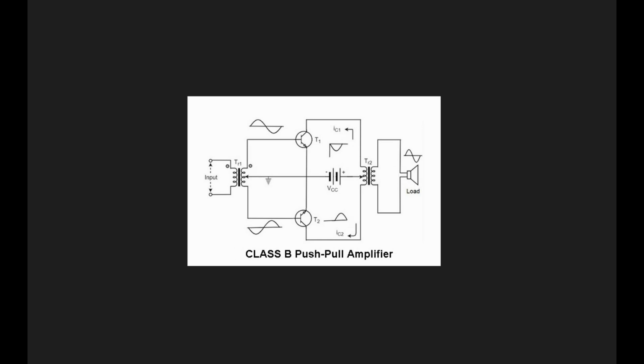The Class B amplifier, this should all be familiar. Those are popular certainly for audio amplifiers and for some linear amplifiers. Class C, the conduction angle is cut down, and usually for RF service we use a tuned circuit on the output, but we don't have to. We can take a little bit of an efficiency hit and do Class C with broadband transformers, but someplace you're going to have a tuned circuit with Class C.